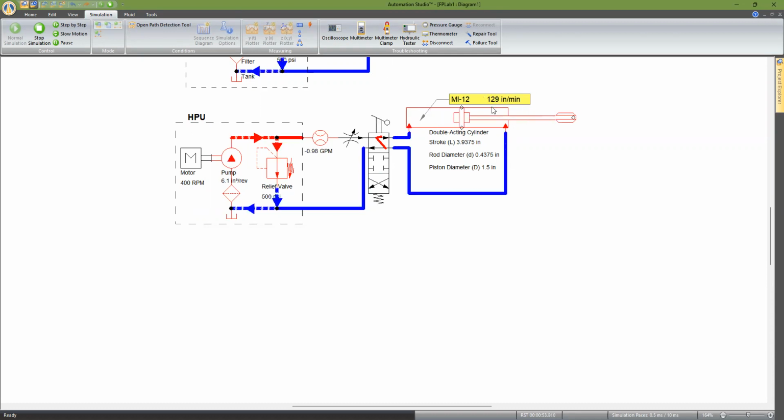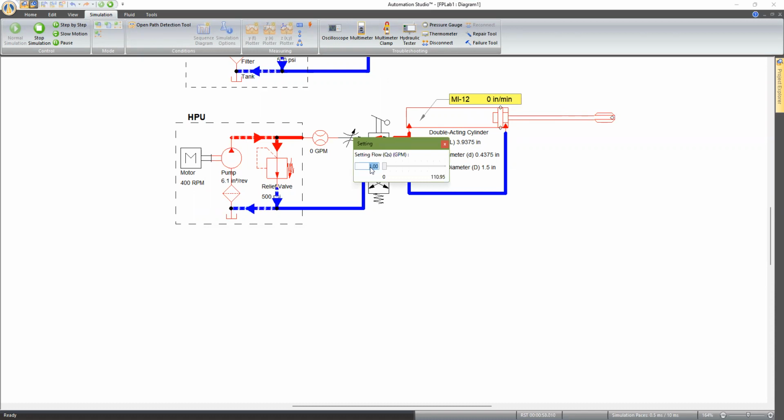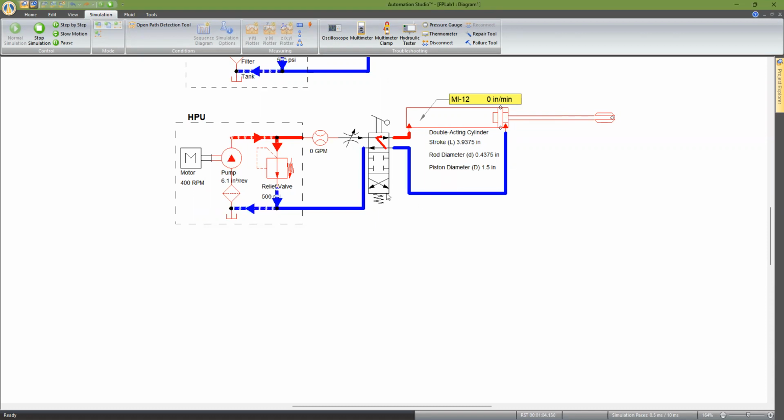Now, sometimes reading off it could be very challenging. Let's say if I have a flow rate of 2 gallons per minute, enter. What do you expect? The rod speed is going to be faster. Okay, so let's do that retraction now. It's really fast. Now, extension, also very fast. Sometimes it's crazy fast for a human eye to read the value. So extension is 259, retraction is roughly 283.